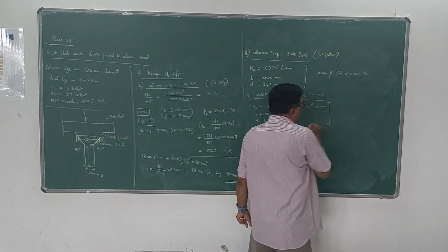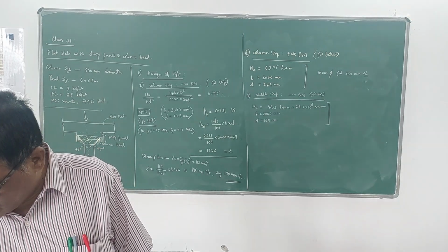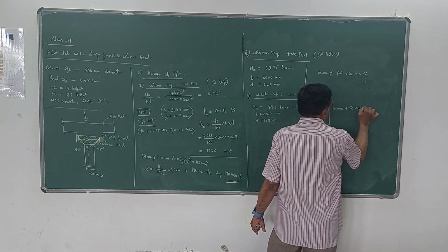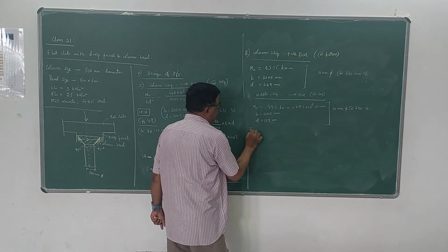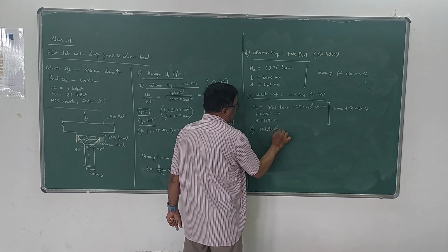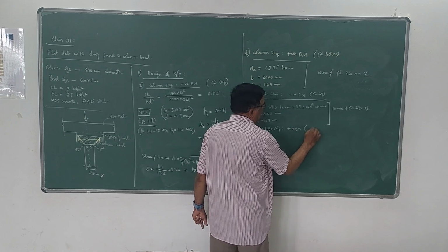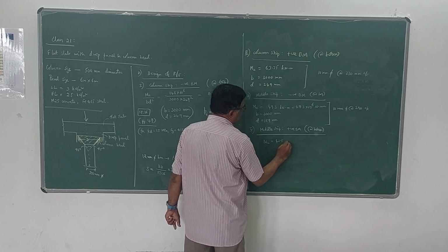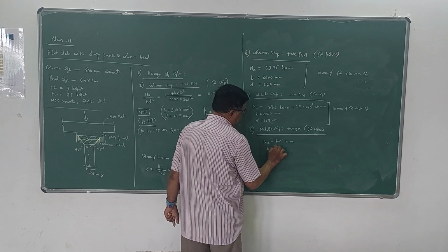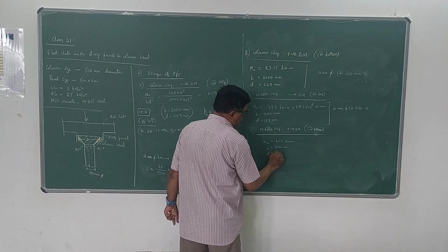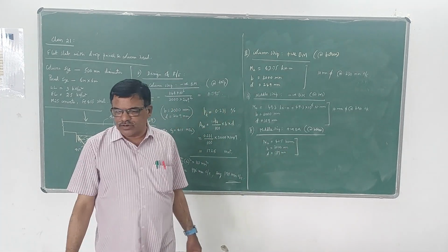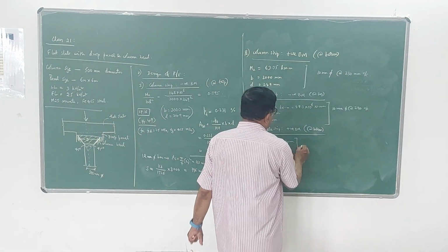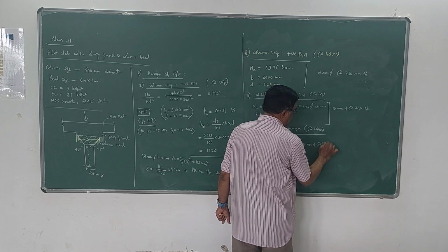Okay, so these values you have to take, and we can assume 10 mm dia bars because the moment is less. So 10 mm at 290 mm center to center. You can just check this. And lastly, middle strip positive bending moment, at bottom we have to provide. So here, what is the value of MU we have to take? 42.5 kilonewton meter. Still less. Of course, B is the same 3000 mm. D is 189. For middle strip, the effective depth is less. If you calculate the reinforcement, 10 mm at 290. So these two will be same, 10 mm at 290, because the moment is less.